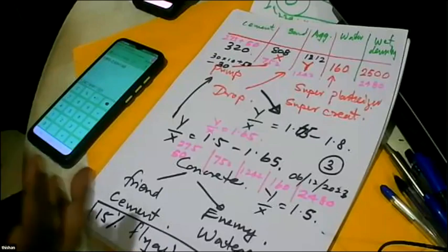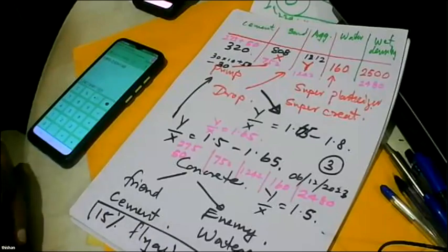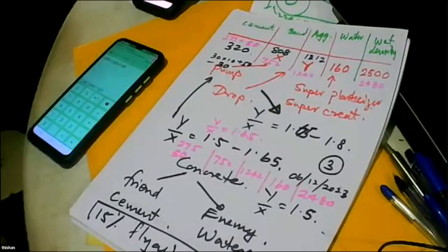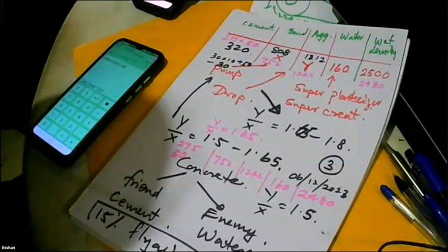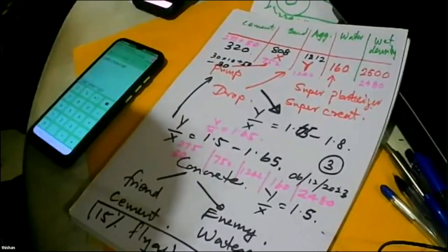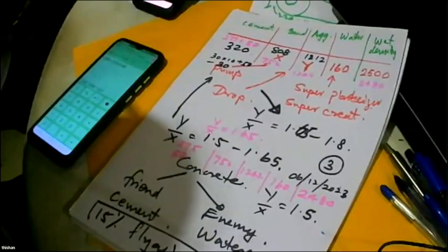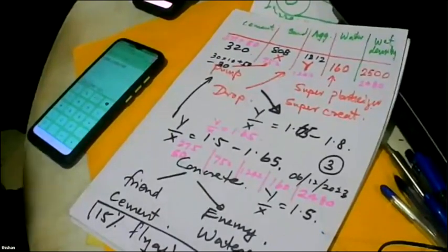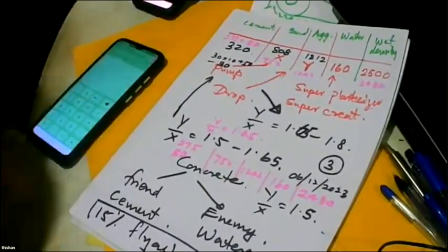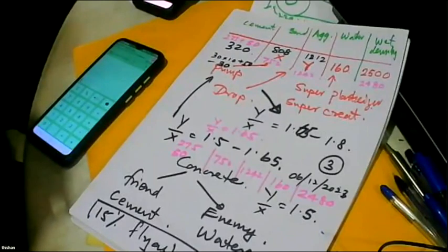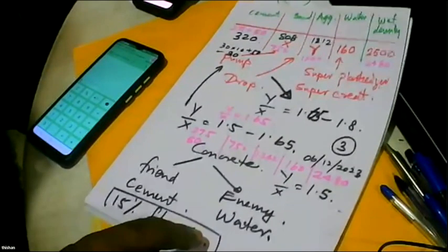Can you see how to think about optimizing the mixes? Bashita, is that clear? Yes, sir. Clear. So as a structural engineer, now you have to do this 3 meter thick raft. You are designing it. What will you select? 30 megapascal or 40 megapascal? You have the option of selecting 40 as well.